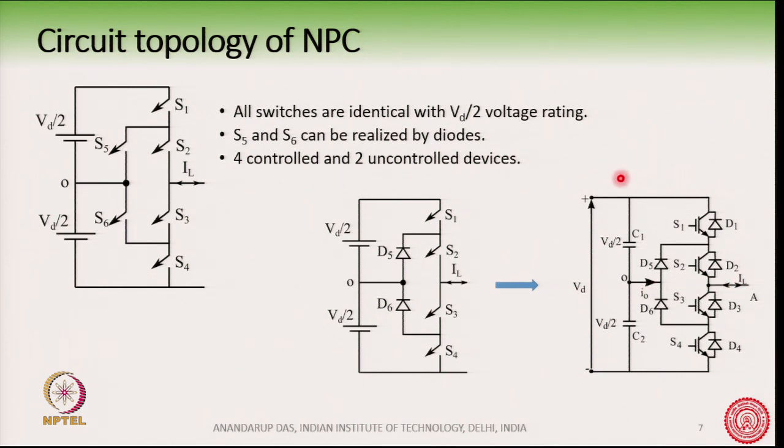So, the overall converter, the neutral point clamp converter, for one phase looks like this. You have 2 diodes, okay, like this, and you have 4 switches. The 4 switches all have transistors with antiparallel diodes. Okay. These diodes D5 and D6 are called clamping diodes, because they are used when the 0 point or the 0 voltage needs to be accessed. We will see this operation just now.